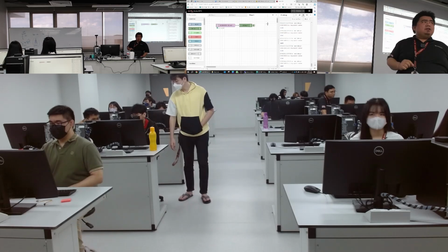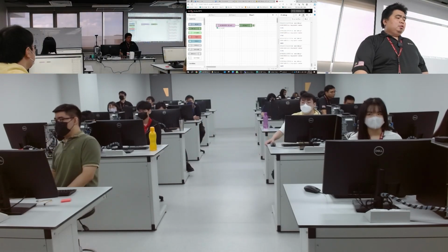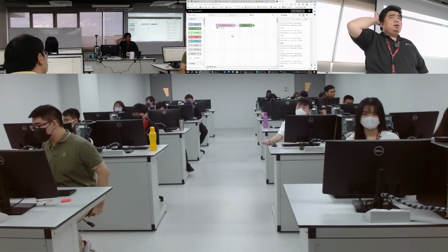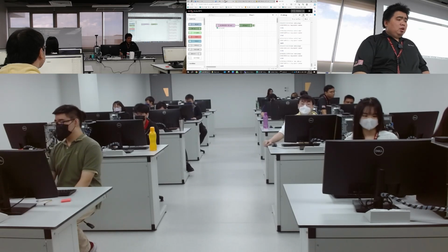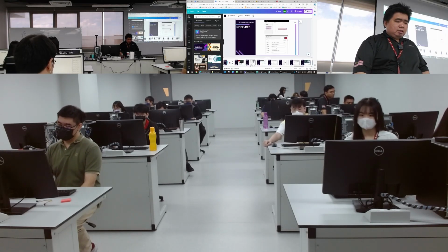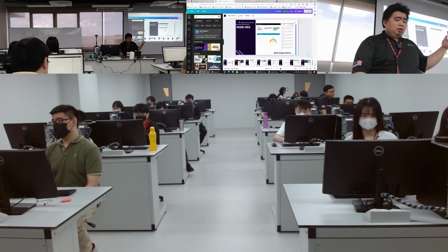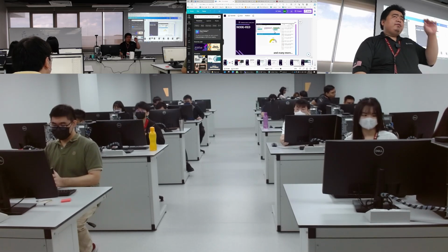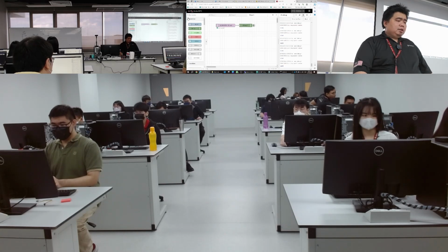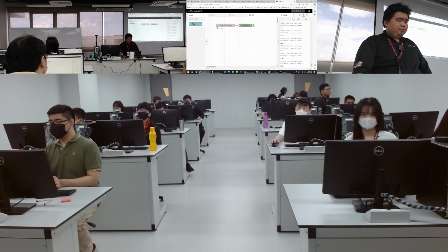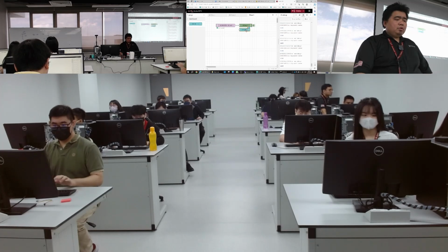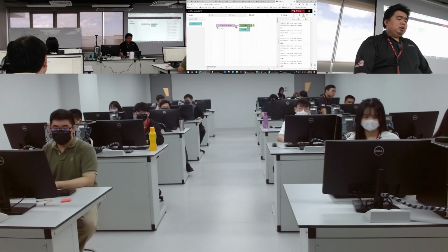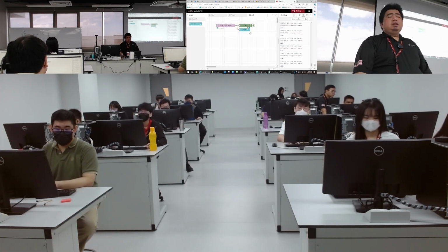So when you get the value itself, we can transform it into something else, right? So either you can refer to my slide or you want to follow my step. It is up to you lah. Right, so in my slide, I stated here, this is the setting for MQTT. Then I try to add a gauge, a meter, right? So if we have a clean value, we can add the meter. So we put it gauge. Dekat bawah ni. So debug basically to display for your debugging and gauge for your visualization, right?